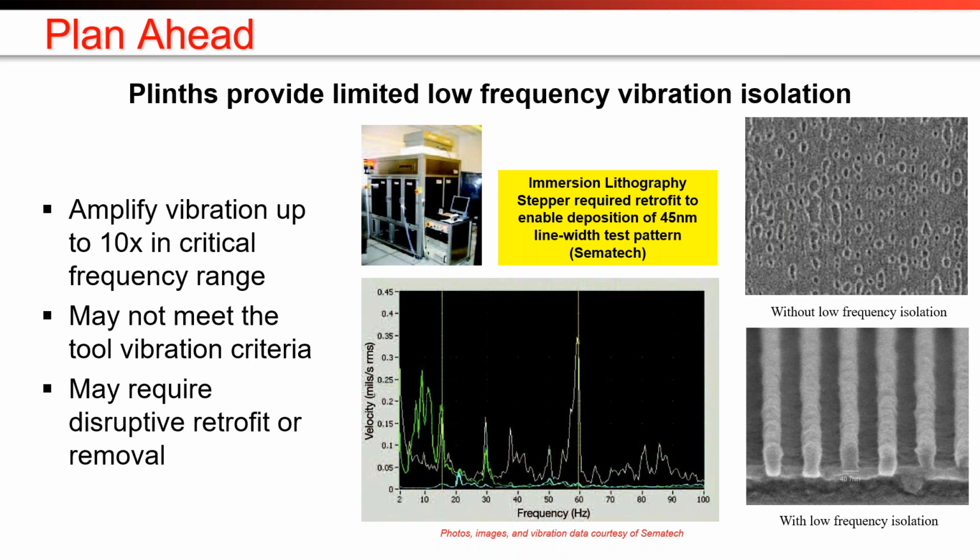It's a lithography tool, so it was trying to put down the pattern that you see at the bottom right, on a silicon wafer. And the plinth was a combination of concrete and steel, bridging the gap between the raised floor and the subfloor below it. And the performance was very poor, and they were not able to create the pattern.